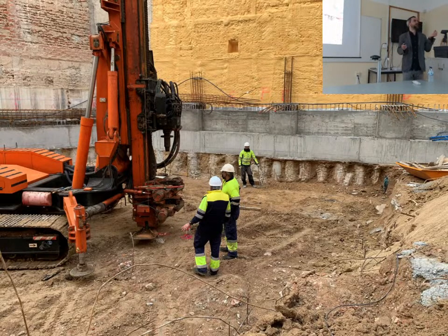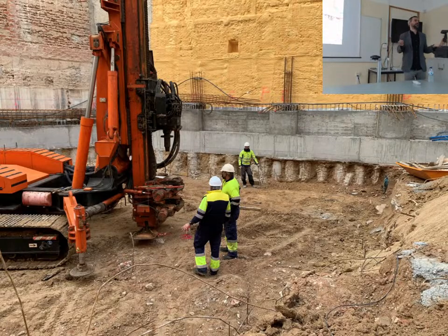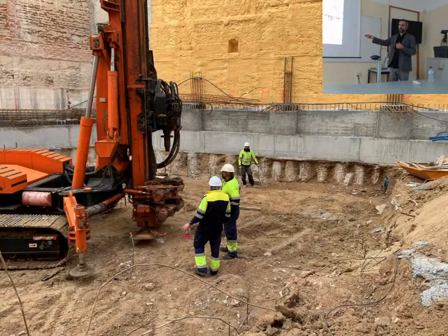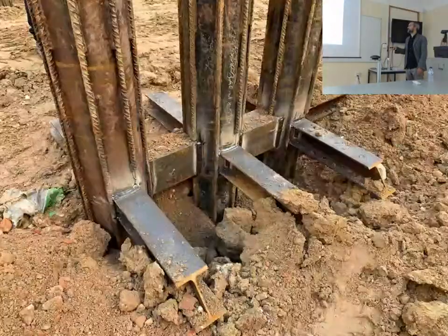We changed a little bit during the construction process, and we decided, instead of starting on the ground level, to start on the -1 level. So you see, we pre-excavated one level. It was just a matter of economy, to try to reduce the budget a little bit. So we started on the -1. We did these micropiles, these quite big micropiles. On this level, you see the connections for the slab we are going to pour directly on top of the soil of the -1. Okay?